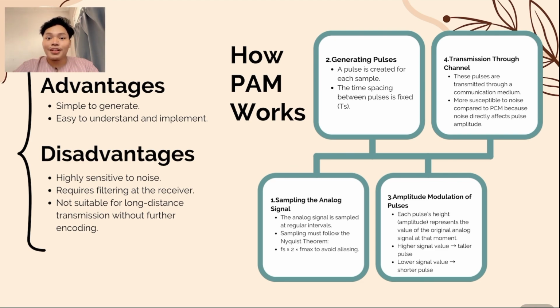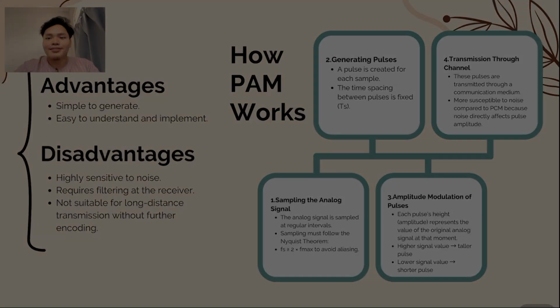amplitude. Now let's see the advantages and the disadvantages. The advantage is that it is simple to generate and easy to understand and implement. The disadvantages are that it is highly sensitive to noise, requires filtering at the receiver, and is not suitable for long distance transmission without further encoding.